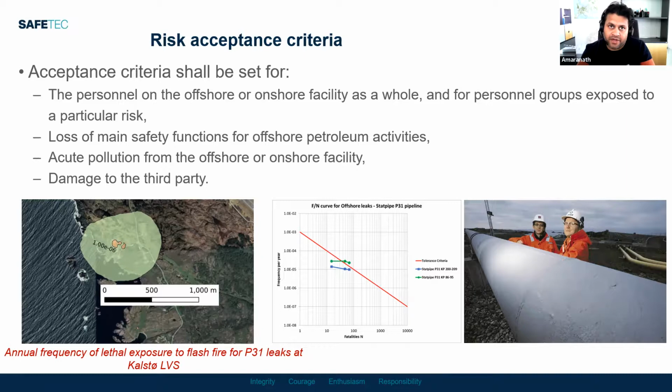Free spans are suspended pipe sections on the seabed. Suspended pipe sections have a higher potential of being damaged by trawling and anchoring, so we need rock dumping or some other mechanisms to avoid free spans on offshore pipelines. But when it comes to onshore pipelines, there are some regulations in OGP,